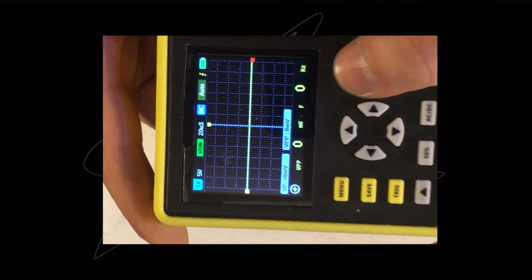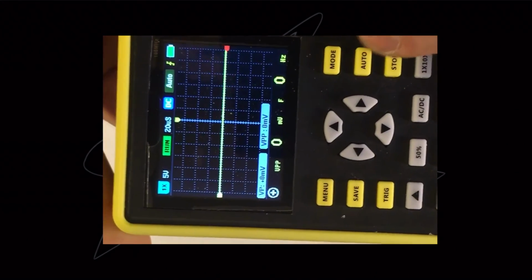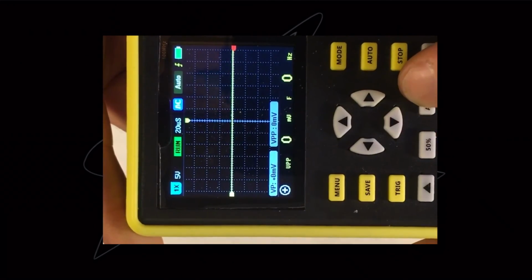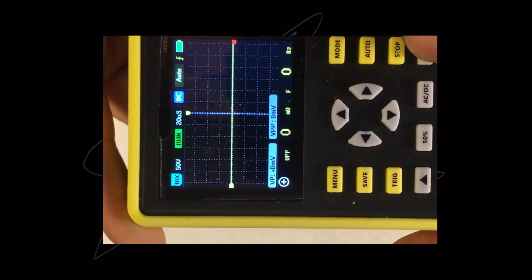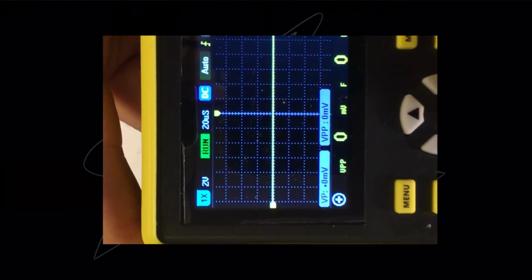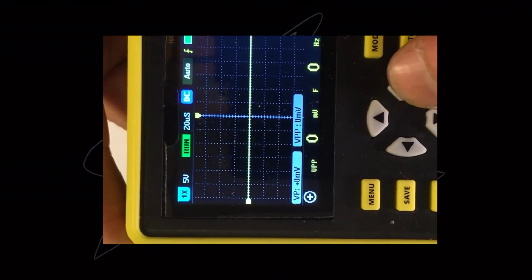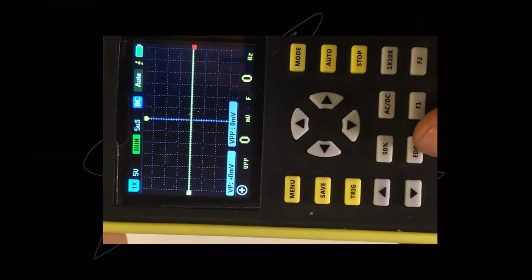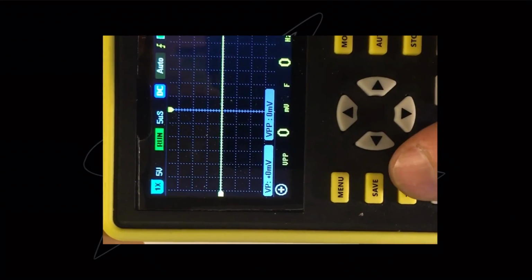We do have the dual channel ADC that we're interleaving into double the sample rate, but even if they're lying about the 500 megasamples and it's only 250, and you split that into 125 and 125, that could be two channels of a scope that you could say is 20 megahertz bandwidth with reasonable certainty. Certainly for sine waves, maybe even with some firmware tweaks for cyclical square waves, you could recreate them, or just regular single shot square waves and pulses, as long as you don't need past the fifth or sixth harmonic or something like that. You're not going to get the seventh or eighth harmonic at 125 megasamples, but you know, still decent enough.